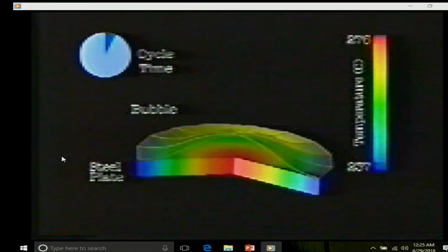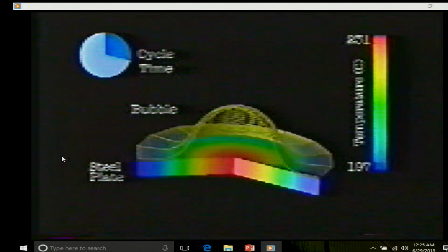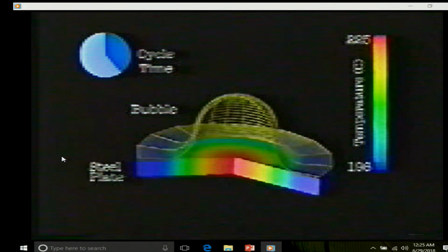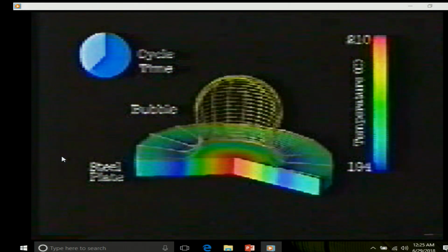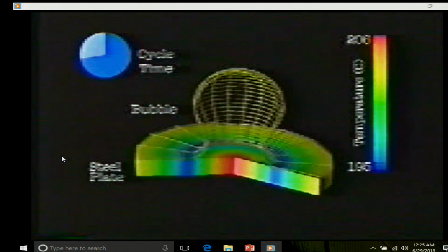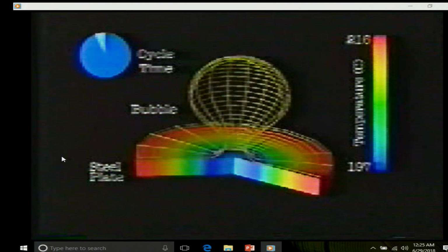Normally people put a thermocouple in the heater about a millimeter below the surface. To begin with, it is a 1 millimeter thermocouple, and it is a millimeter below the surface, but all that fluctuation in temperature is occurring within the first 50 or 100 microns of the surface. So, a big thermocouple way below will not be able to see it.